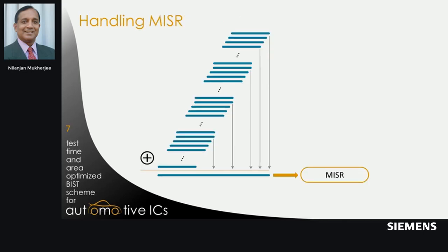The next challenge is to calculate the MISR signature for all these patterns, especially when they are distributed to numerous slaves. Fortunately, since MISR calculation is a linear process, each one of the slaves is responsible for calculation of the signatures for the parent and intermediate patterns. And once they are calculated, they are sent back to the master, where the final MISR signature is calculated based on the simple principle of superposition.